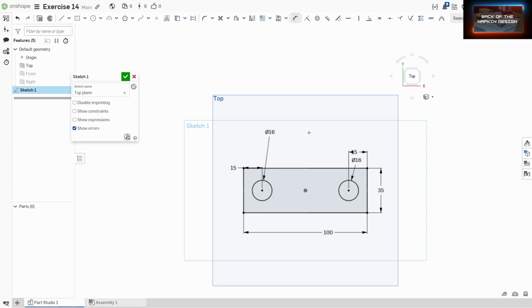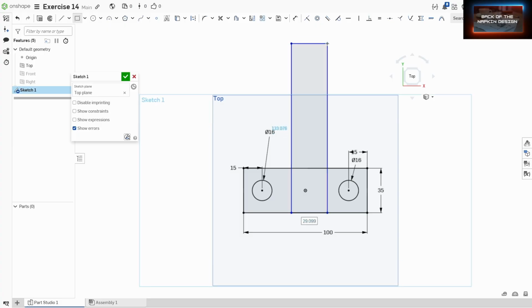Next we need to build another rectangle up here. So let's build that, and this is going to be 110 millimeters from the bottom. So we can change this to a corner rectangle now, and might as well go from here all the way to here, and we can hit D for dimension. This is our origin, so this is really important. We can take everything off of this. So this here to the left, and the width of this is 20 on one side, and D for dimension to get that back.